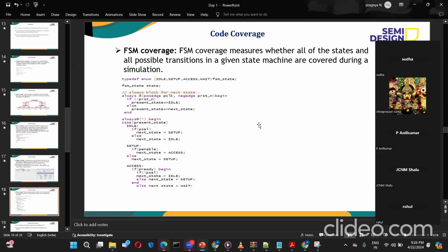Then you have to update your coverage plan. Initially, you create a rough coverage plan, and based on your understanding, you update it. Okay, this requirement is not there, so we don't need this. Or there could be some special cases. You may think that this is some priority feature you observed in the test plan, and everyone is focusing on that. Then you have to note it down in your coverage plan: this thing I need to sample, this thing I need to cover, this scenario should be covered at any cost. If you note things that way, you will not miss the important things. So that's how the coverage plan is done.